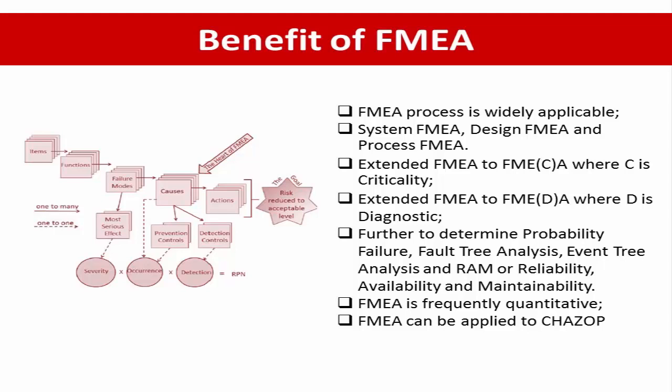So, FMEA can be further developed by determination of the failure probability, failure fault analysis, inventory analysis, and RAM, or reliability, availability, and maintainability. Since the FMEA is performed based on known failure modes, the FMEA technique can be applied to review the control hazards and operability analysis, or HAZOP.